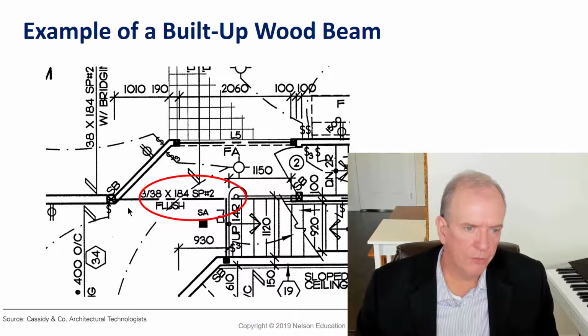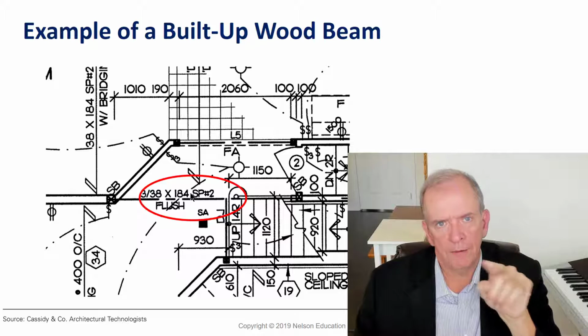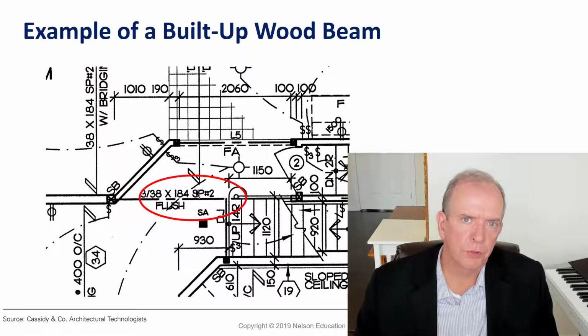So here, on a set of drawings, it might say something like 3-38 by 184, SP number 2. Now that I'm thinking about it, I don't think I mentioned SP in the previous lecture. From the grading stamp, it says SPF on the grading stamp. That stands for spruce, pine, fir. On the drawings, if you see SP, that refers to spruce.